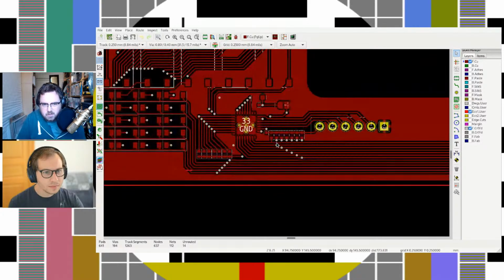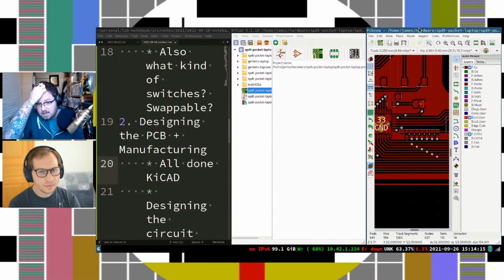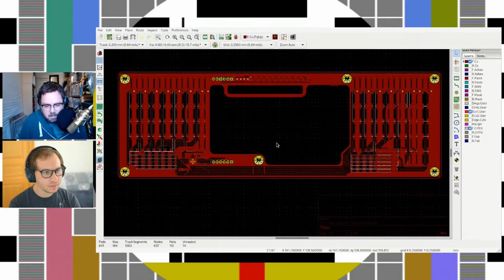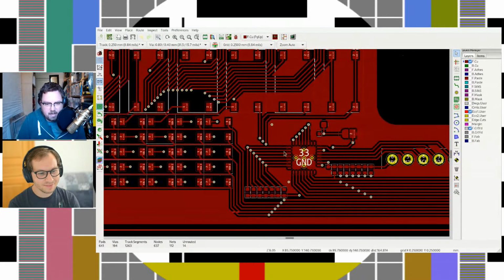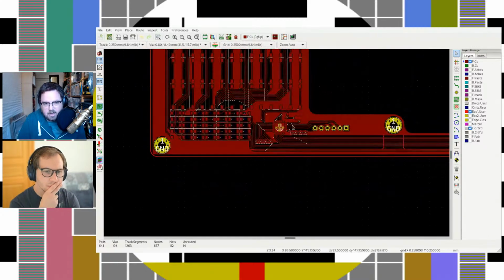And then pretty much all of these tools nowadays can just, in a couple clicks, export this into Gerber files, also with the position of all the drills and the components. And sites like JLCPCB are really cheap nowadays. I think getting 5 or 10 of these built cost me like $80 or something like that. Right. And they had essentially everything. I had a little port expander chip that's doing all of the control of the switches. I'll show you here in a little bit, but all of the diodes and resistors that are required for the keyboard, I can have that all built for me.